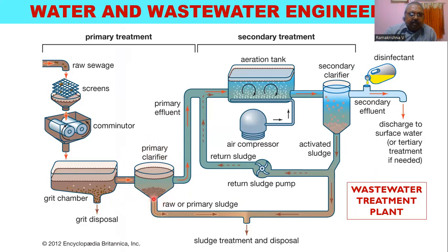And what are the particles which settle down to the bottom? They are called sludge, and because they're coming through the primary sedimentation tank, they are called primary sludge. So we'll talk about the design parameters of the primary clarifier and simple calculations. There are two shapes of primary clarifier, circular and rectangular. In general, circular clarifiers are more preferred in wastewater treatment plants.